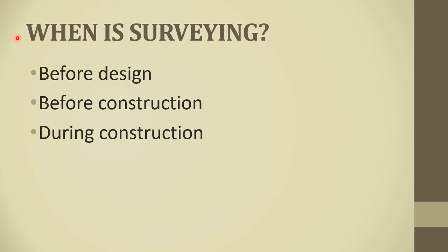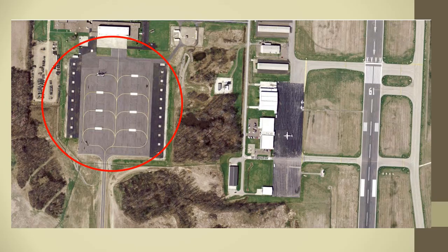We have to do it during construction because the survey points that we put in before construction may have been moved, or we need to make additional measurements during construction. And then we have to do it after construction to see if the project has conformed to the plans.